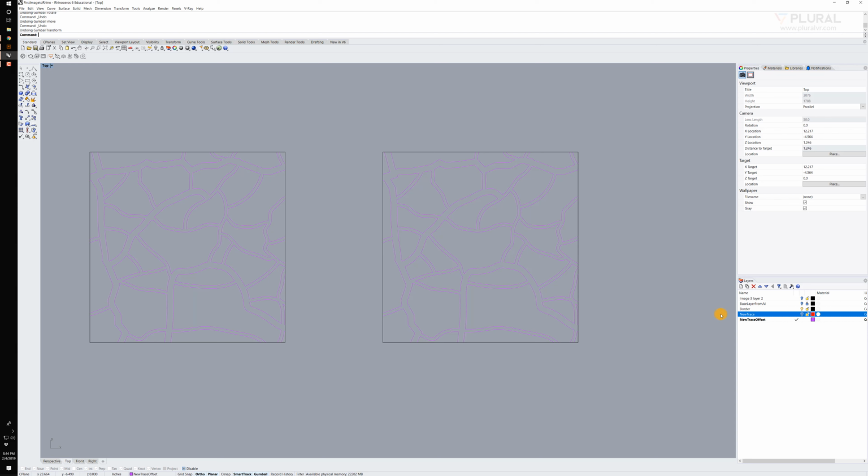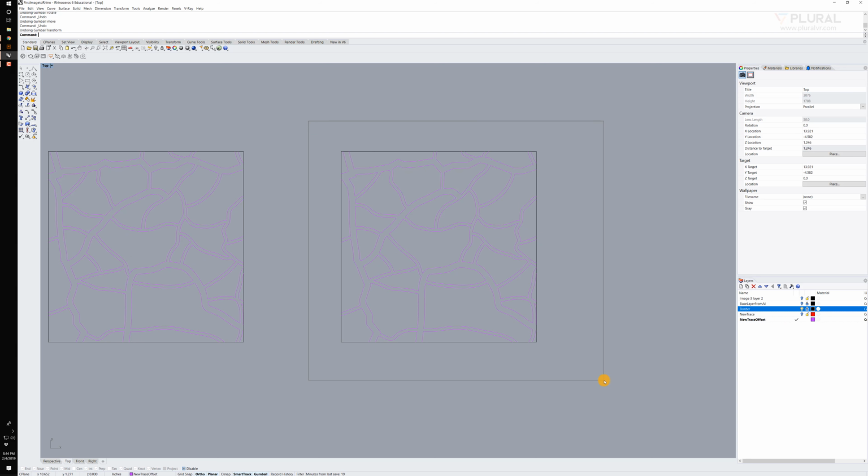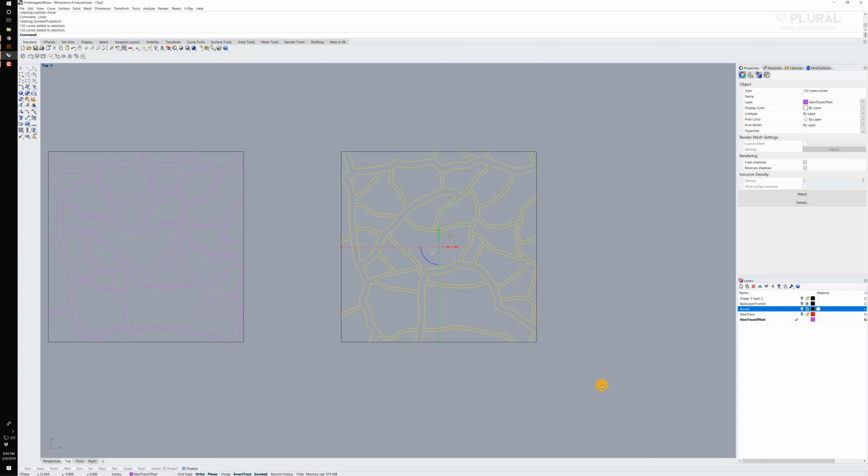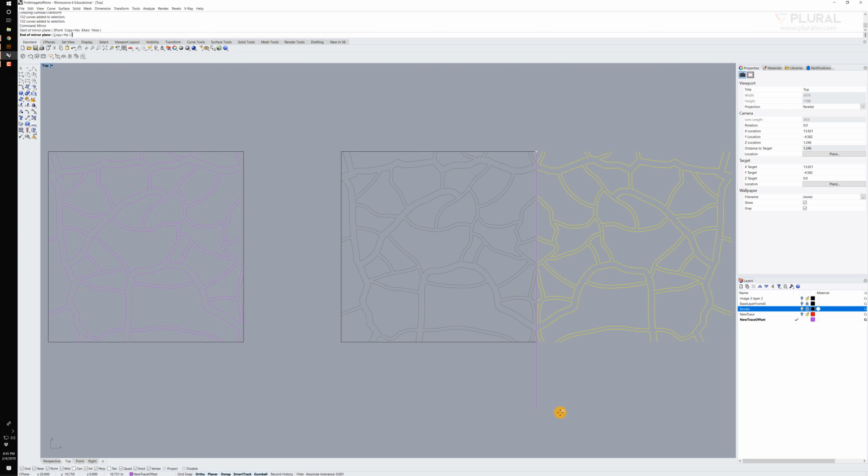All right, let's go ahead and lock our border. This way we can't edit it. This is our trace offset. This is our layer 1 offset. I'm going to drag from left to right to select all of it. I'm going to use the mirror command and mirror it over our border edge by turning on my O snaps, clicking the endpoint of my border and dragging down.